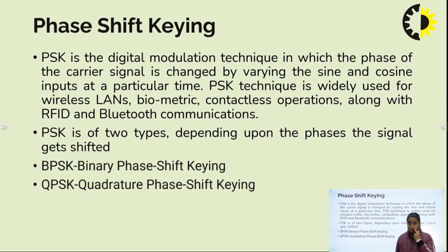First of all, I would like to elaborate about what BPSK is. BPSK is the simplest form of PSK. It is binary phase shift keying. Here, the phase shift in my modulated wave will be of two variations: if we get a phase variation corresponding to bit 0, there will be a different kind of phase variation corresponding to bit 1, right? So this is the simplest form of PSK that we are going to study, which is called binary phase shift keying.